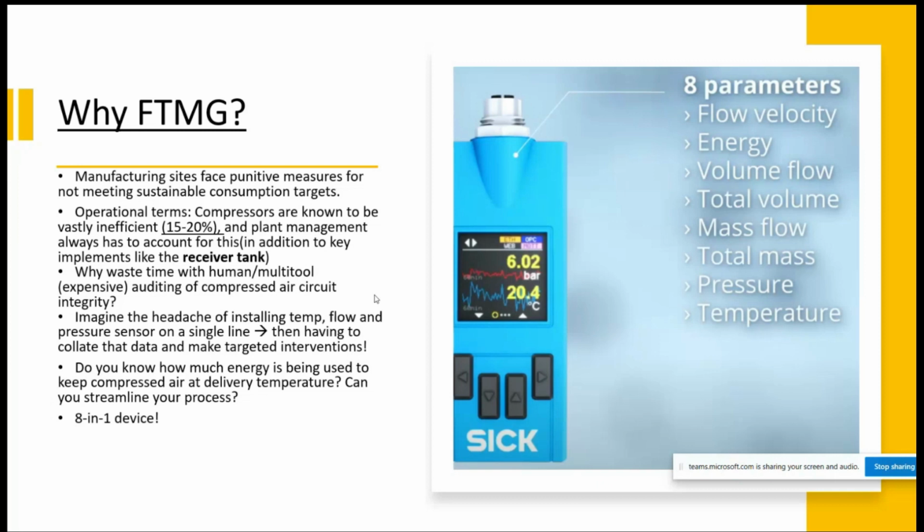And in your compressed air circuit, you've got items like a receiver tank that will accumulate the compressed air at the ready delivery pressure and temperature. You've even got cooling sections as well, like a cooling dryer. So there are so many sources of loss here, and just the effects of integrity of the connections as well. That's where the gas is going to slip out, not just from leaks in your line where the line itself is eroded and opening up.